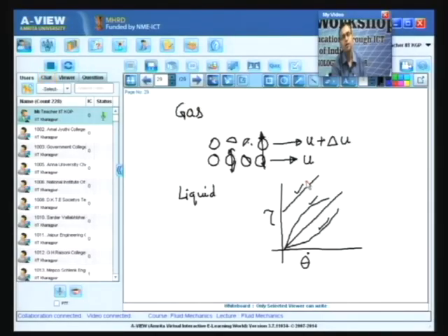But there are other types of fluids. You can have a non-linear variation of viscosity, and the non-linear variation may be of several types. Even there can be a linear variation, but with a shift, with a yield stress. So, these different types of fluids are not Newtonian fluids, and their behavior can be attributed to their peculiar rheological characteristics.